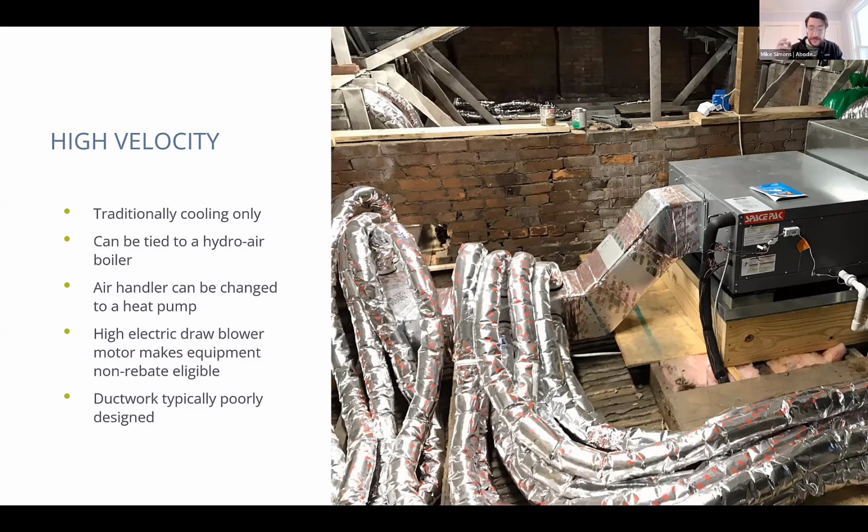The reason this traditionally exists is that there are lots of homes where you can't fit a 8-inch or 10-inch duct. So some people with older homes trying to retrofit them for central AC would do a high velocity system. Instead of a standard register, it uses hockey-puck-sized vents scattered throughout the ceiling, or say, throughout the floor.